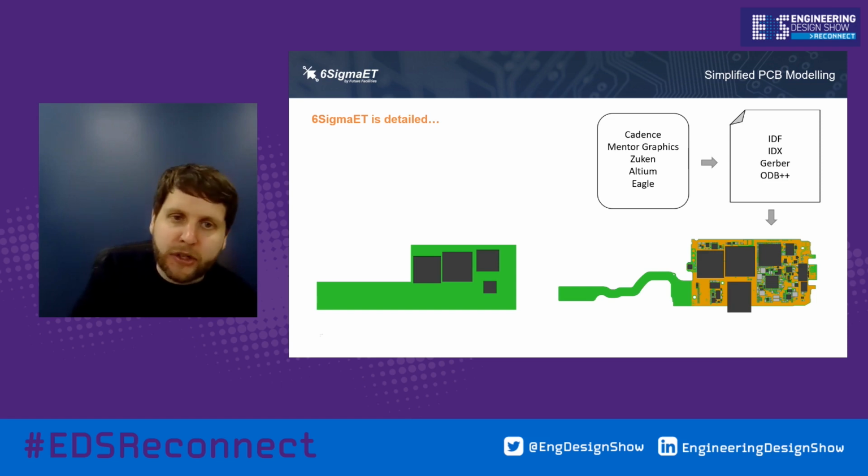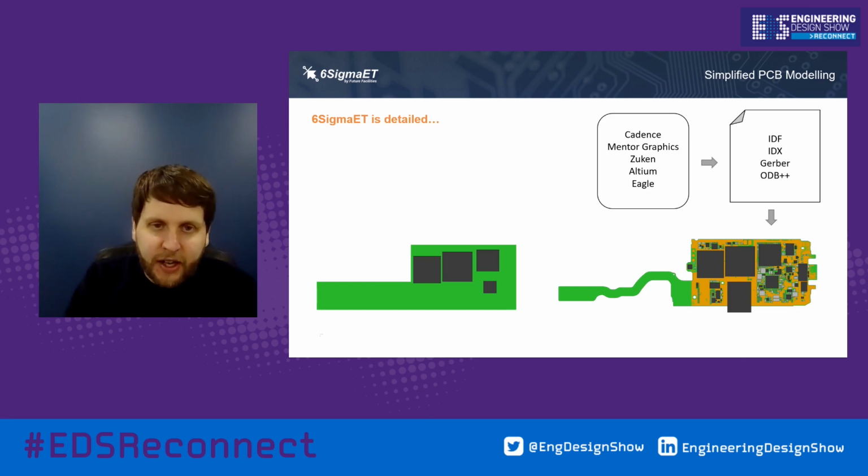I would encourage you to do what's on the left-hand side, which is to model the printed circuit board simplified first, with the rough component layout and the rough PCB outline, and see if there's any problems with that first, which can then help guide the PCB design and make sure that there's no late stage design complications.